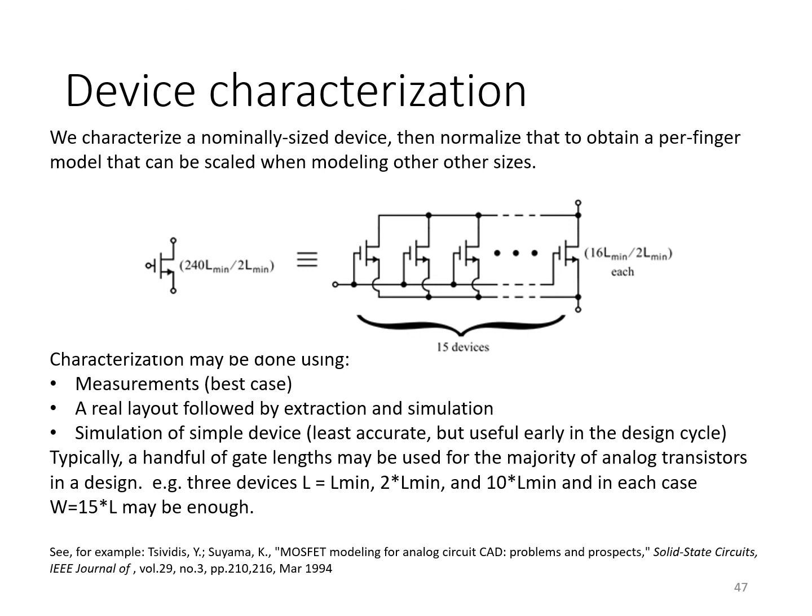parasitic capacitances, for example. Now, the reason you don't want to characterize just one finger is because, as we showed before, when you have a multi-finger transistor, you get to share a bunch of source and drain regions, and that reduces the associated parasitic capacitances.